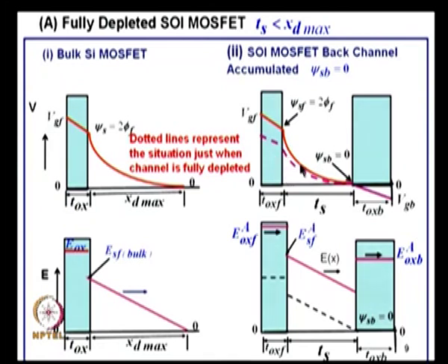As the depletion layer widens, because of more and more plus charges at the front gate, more and more negative charges come from the substrate, and there is more and more widening of the depletion layer. At a particular point, you can call it the punch through voltage, the depletion layer has completely merged with this point. That is the electric field distribution there. Similar to this, but this field will be much smaller than that, because this width was large, 1 micron let us say, and that has not depleted.